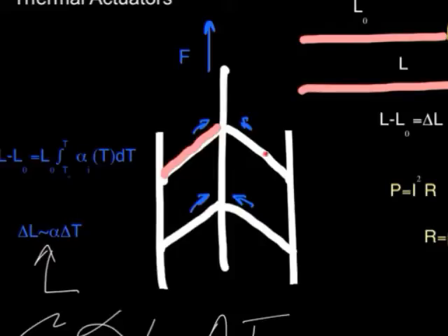If I heat these legs up, they'll want to get longer, and the way they're arranged in this chevron pattern, that's like a V pattern, each one of these will get longer, and the resultant will be to push this beam up. Okay, if I heat these up, and then you'll get some force.